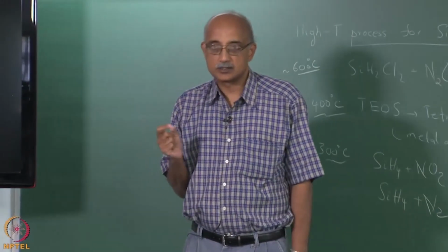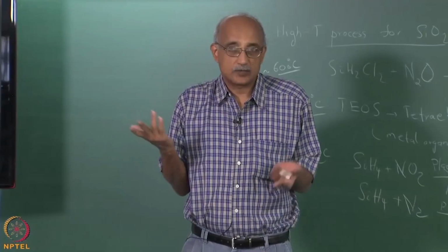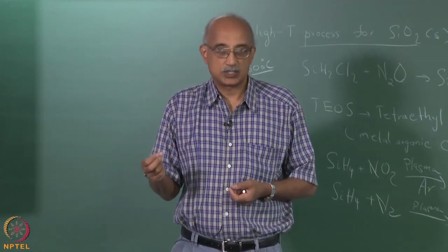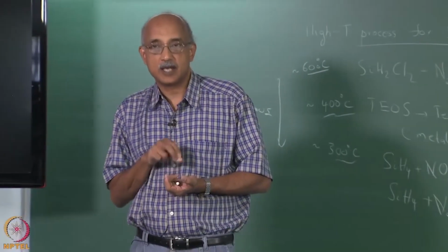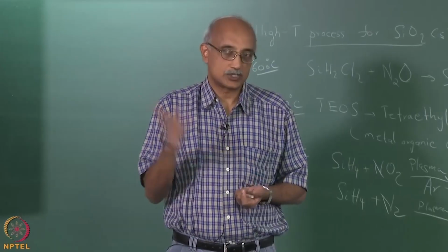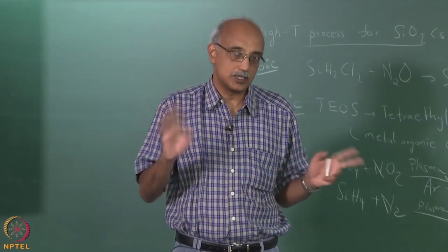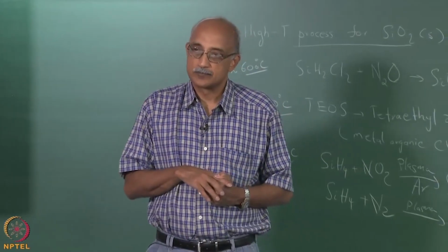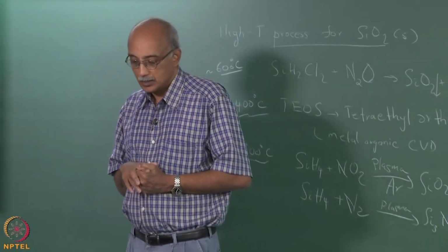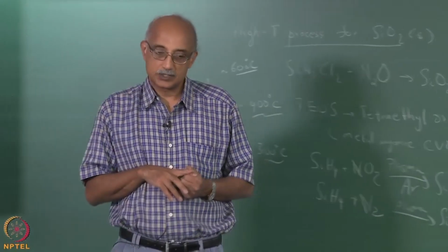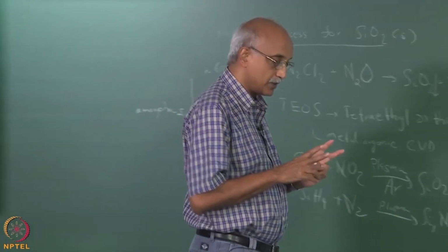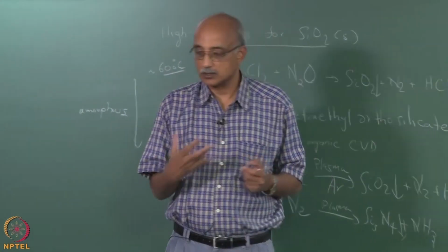If you have inert elements, obviously you cannot even do CVD, right, because you can only do PVD. So, by definition the depositing element has to be highly reactive in order for us to even consider a CVD process, otherwise just use physical vapor deposition or other means of making that film happen. Tungsten, because it is a highly reactive metal, is highly suited to CVD, and in fact there are two mechanisms by which you can deposit tungsten on a substrate.